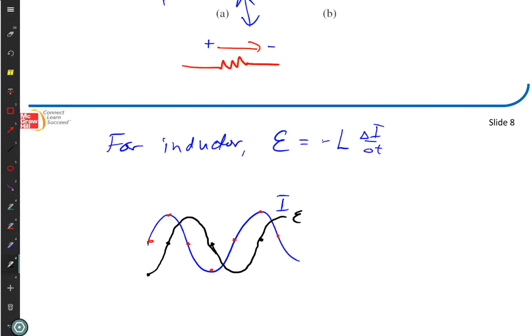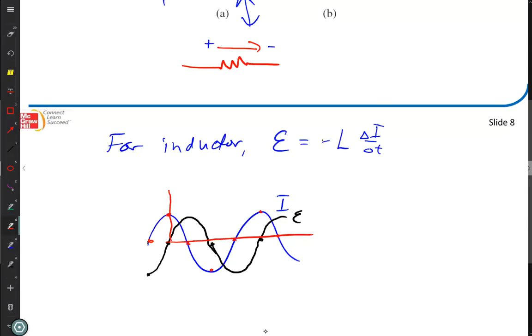Okay, we have people that said current. So just to make sure everybody understands why it's current, because they're correct, if we put an axis on here that goes like this, at time equals 0, the current's at its peak. And you have to get out here to this time before the voltage is at its peak.